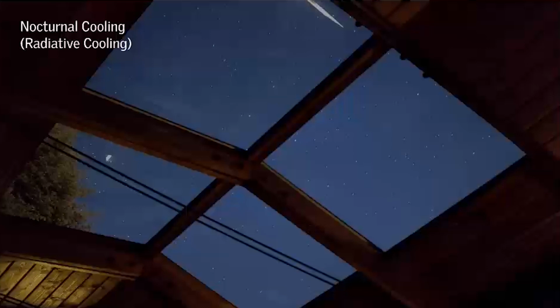So nocturnal cooling or radiative cooling is one of the concerns that one might have with skylights. What happens is that on a clear night, outer space is very cold. Even with our atmosphere, it's still very cold up there. This effect can give us frost on an evening that is above 0 in temperature. So you could have frost on the ground, but it only got to 2 or 3 degrees in temperature.